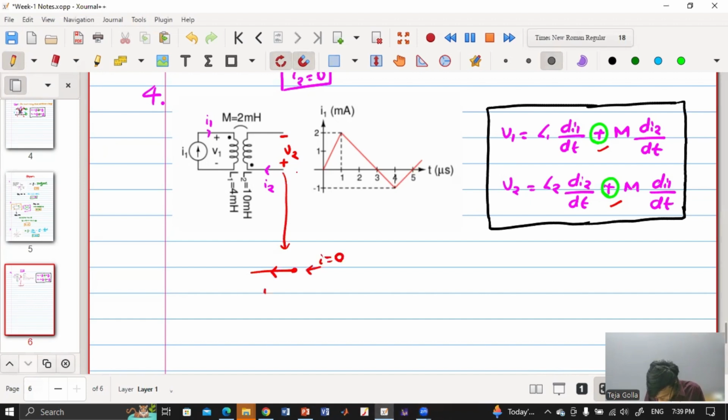So here also current should also be 0, because I have a voltage source, I have a resistor. Only if I connect the voltage source to the resistor, current will flow, right? If I don't connect, current will not flow, because there is no path for the current. So current should have a path to flow. If there is no path, or if there is something open in the loop, current will not flow. So that's why the current is 0. Then only the KCL will obey.